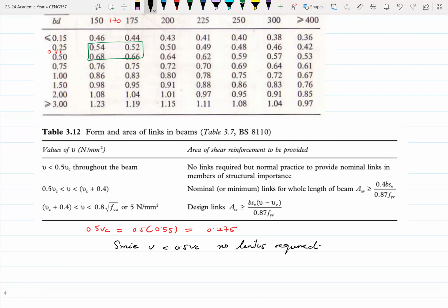So normally what we do as engineers, when we are designing slabs, usually solid slabs, we tend to use a smaller effective depth, or even a smaller overall depth of the slab, so that we don't need to do shear reinforcement. So you realize that for residential facilities, mostly the overall depth of the slab is about 150 millimeters. Or let's say it's between 150 to 200 millimeters, but normally closer to 150 than to 200.